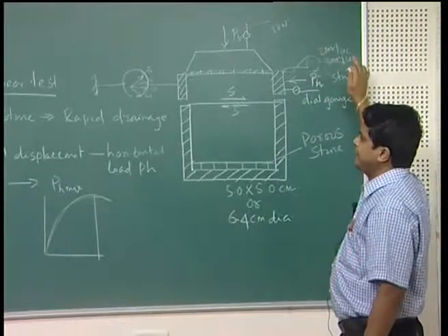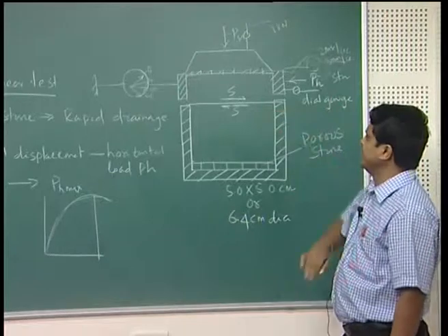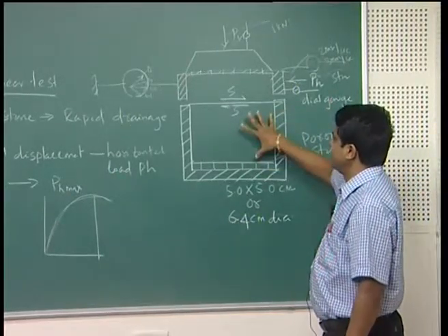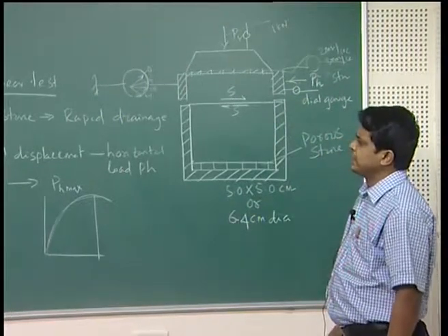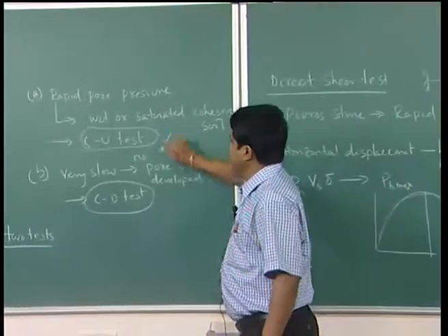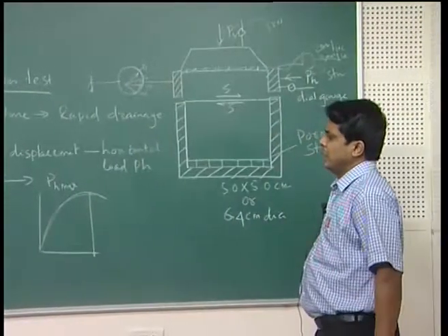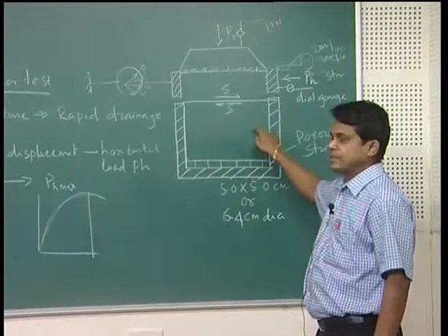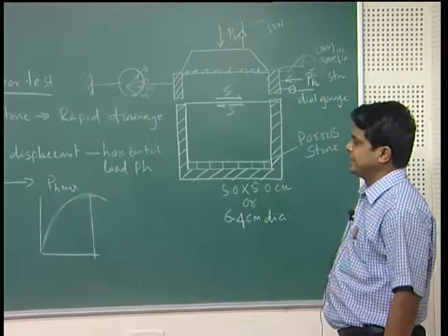That means, if you apply a very rapid displacement rate, what will happen? During undrained condition, rapid pore water pressure will develop. So, this will simulate the consolidated undrained test. Now, can I simulate a consolidated drained test by means of the direct shear test? The answer is yes, I can do a consolidated drained test.